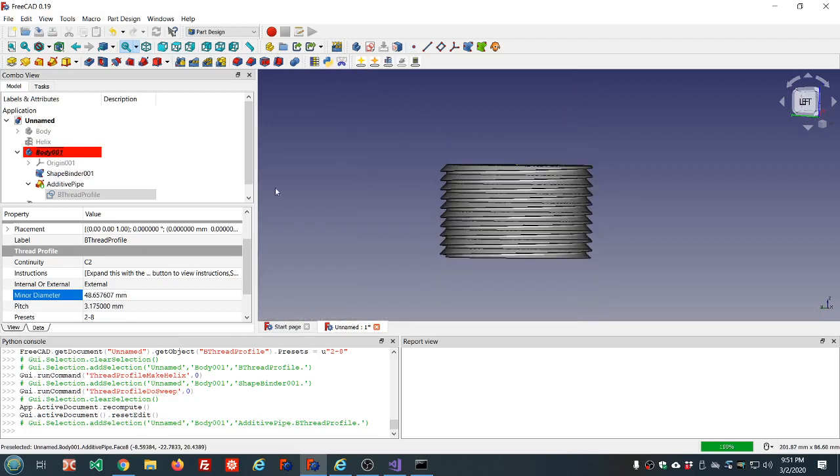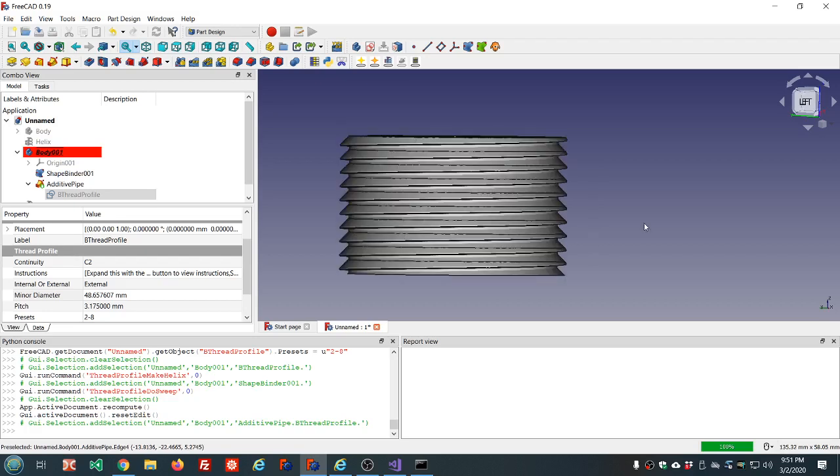So that's why these are all American standard settings. Now in the V threads, you do have metric coarse, metric fine, and you have UNC and UNF, which is the coarse and fine for the American sizes or the imperial sizes.